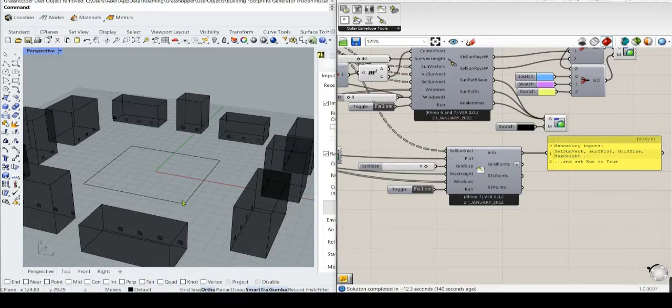This internally is selecting each grid point, and it's checking all the sun vectors and the intersection from each window to each grid point. So the algorithm calculates the maximum height for each grid point. That basically will allow all the windows to receive all the selected sun vectors generated before.